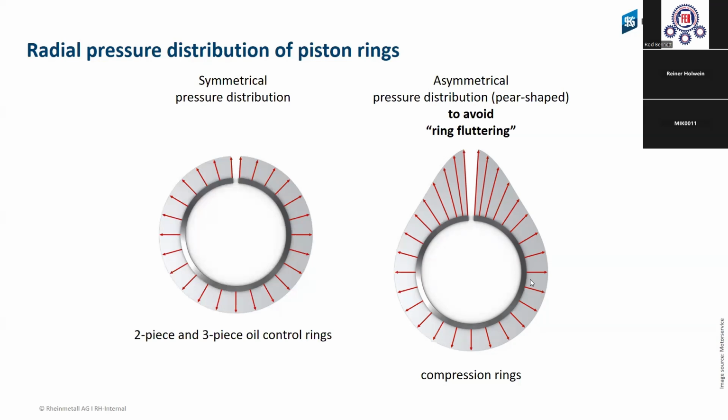maybe longer. And again, when you start the engine, it is better to do it in a higher load position than in a lower load position. And this is also information that you must give to the end user, the user that is using this engine, this truck, this passenger car. They must take this engine a little bit more in load position, so that the engine will be run in very quickly for this running-in effect.